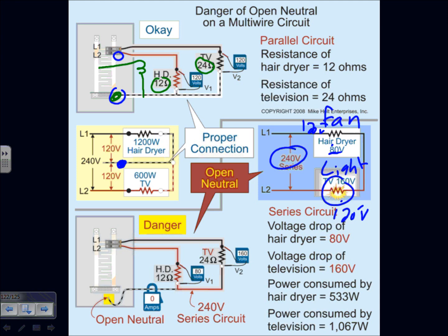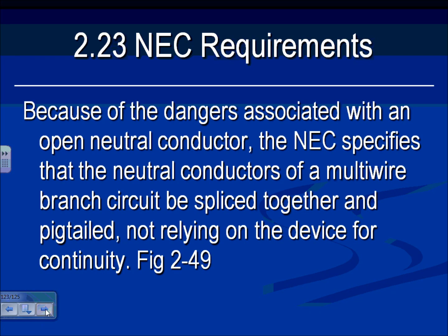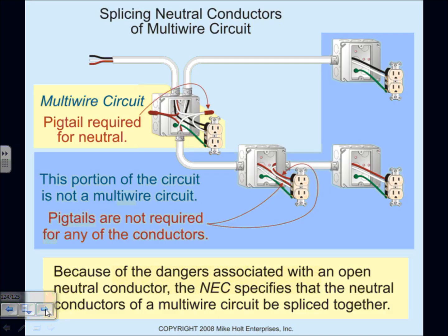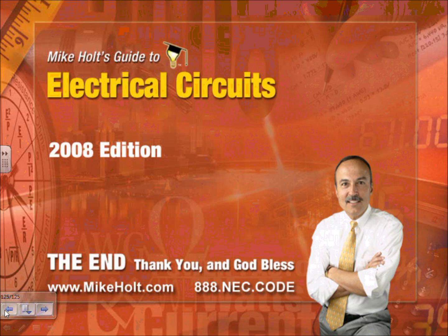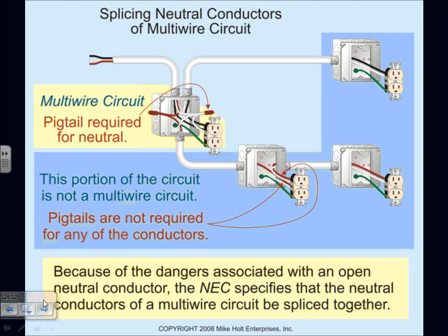Any question, guys, about the danger of a multi-wire branch circuit, three-phase or single-phase? Now, this has nothing to do with design, it's about maintenance. You guys will design a good system, but as you troubleshoot, I can't emphasize enough from my own experience and yours, always be very careful when you open a neutral, especially in a residential or commercial building. Very careful when you open a neutral. Okay, almost done with that one. Any question, guys?